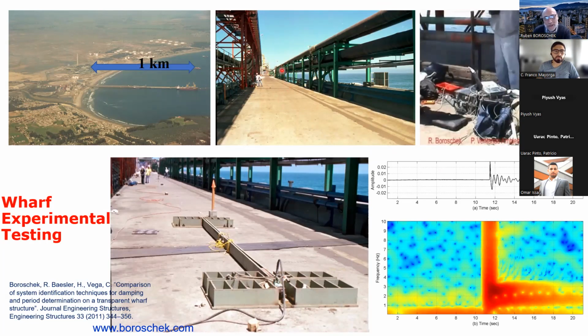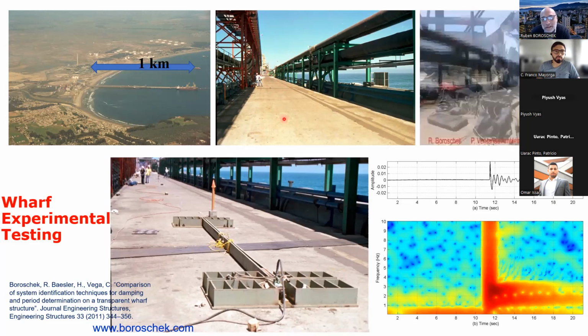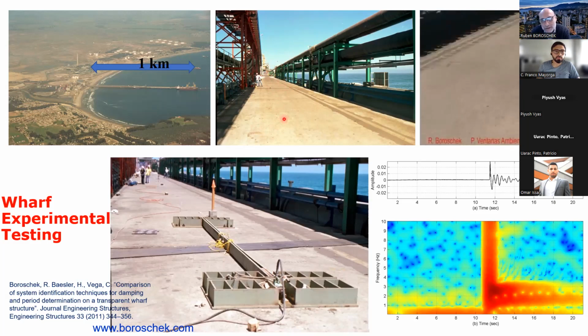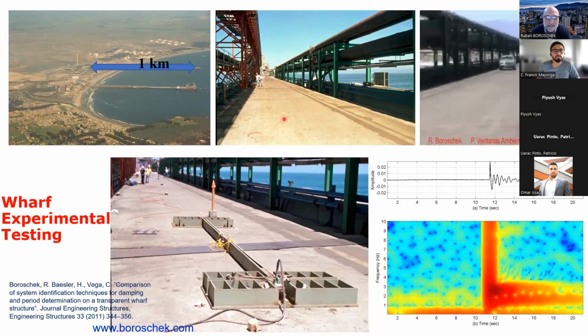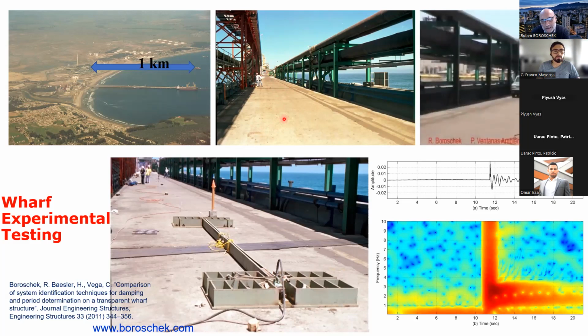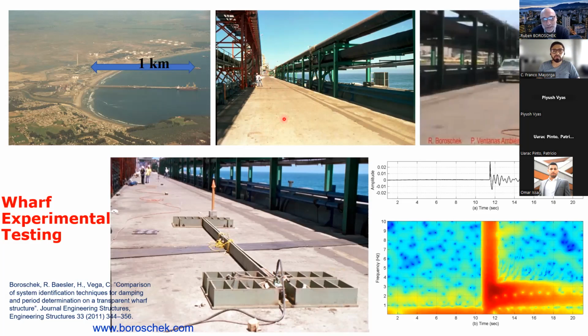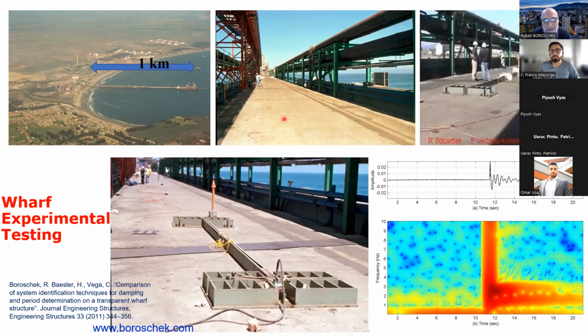And the key issue here for this port was to understand what was the operational damping of the system. So if the damping was below 3%, they need to reinforce. If it was higher than 3% critical damping, they don't need to do anything and just build on it. So you cannot model damping properly, so we have to go and test.